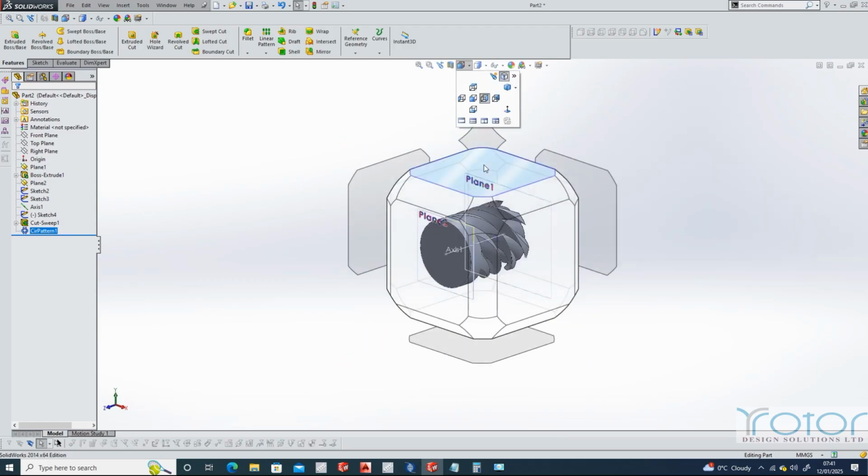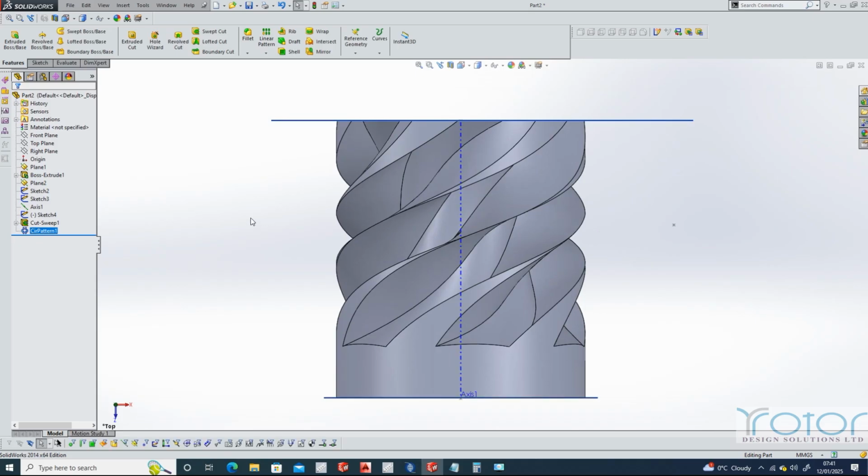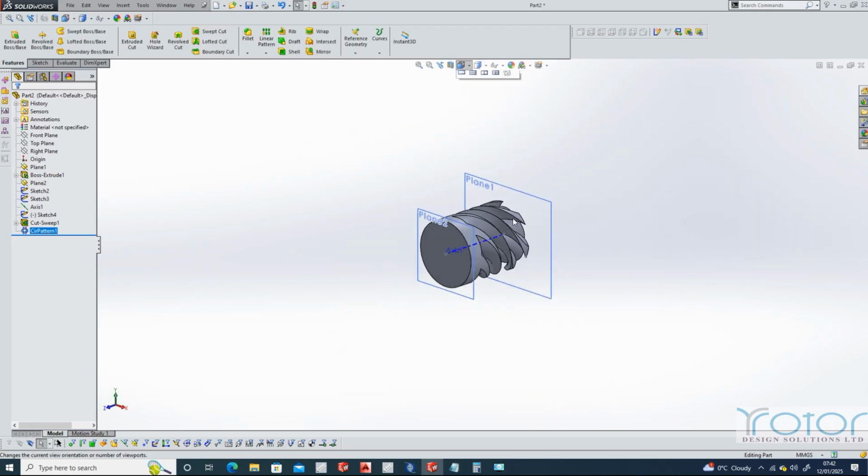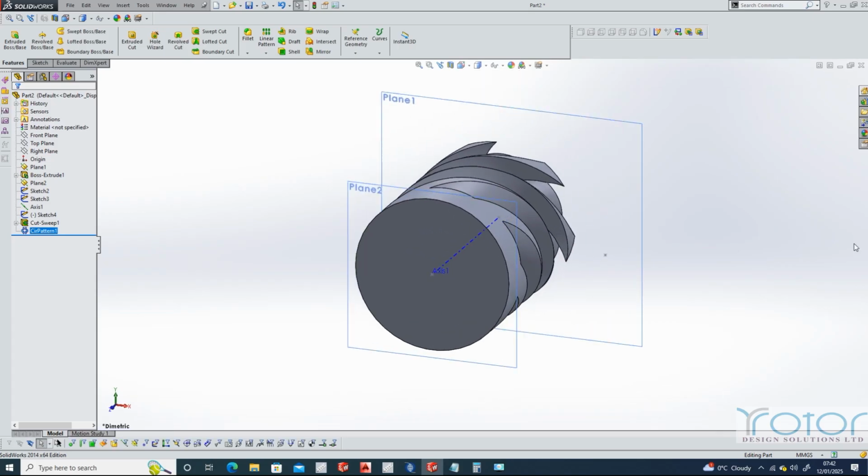Obviously we can change the geometry on this. You can see here that this is getting a little bit thin. There's no OD section here, so perhaps the geometry needs to be modified slightly on the cutting tool, make it slightly thinner. That will give a defined outer diameter all the way around. But that's the basic method that's used for generating a rotor for a single compressor.